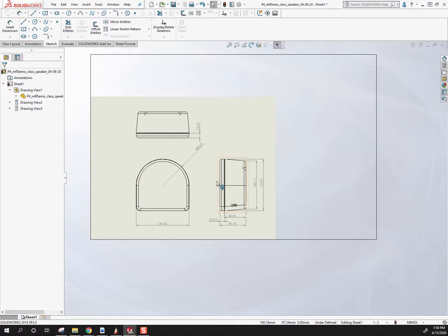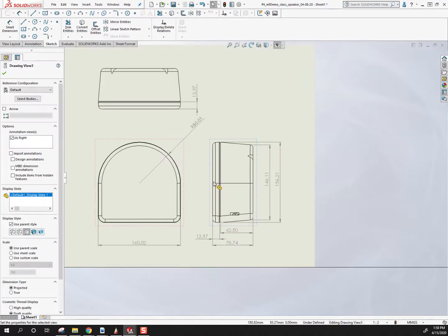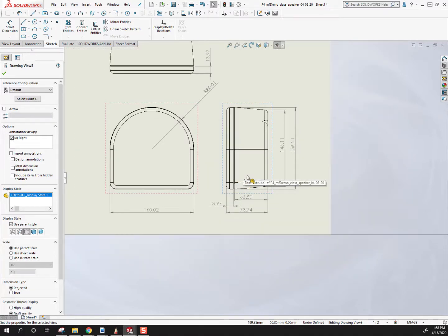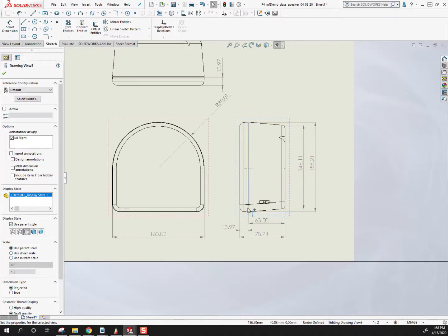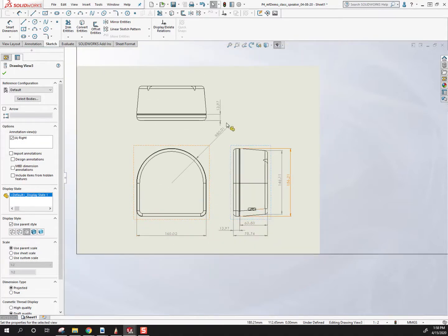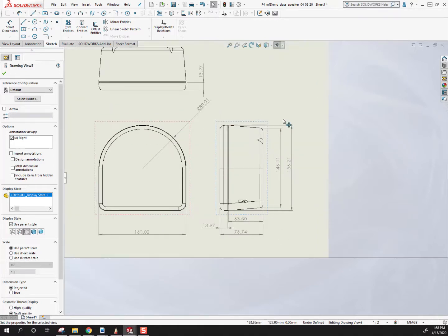The reasoning for that is the goal with dimensioning is that it's easy to understand. So that's why you don't want to overlap or cross them, so that there's no confusion. The reason for grouping them, even though there's more chance of overlap, is that this view from the side then has a lot of information that someone can look at and understand. If your dimensions are on different views, you may have to scan more of the page or look for it. Again, it's all about clarity. If you group them together, you only have to look at one view or one image for the majority of the information, as opposed to having to hunt for it, so to speak.